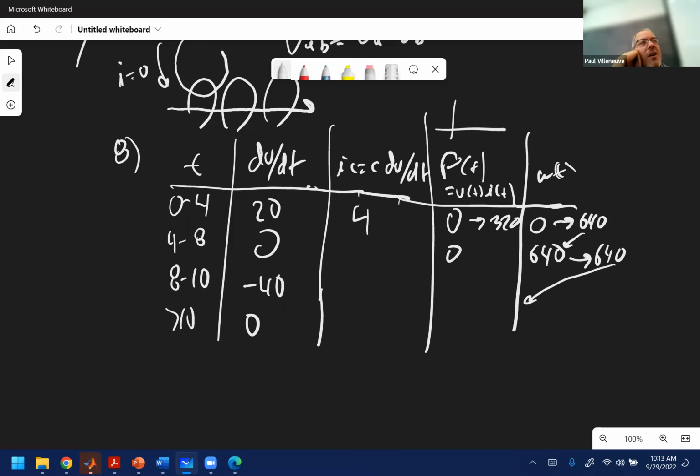But the equation for power of time is called instantaneous power. We'll see that when we start looking at AC circuit analysis. For those of you in 312, for example, the power that you're calculating in AC circuits is not an instantaneous power. It's an average power. But if you actually look at what the power calculation is, it's really take any instant in time, find the voltage and multiply it by that same instant in time current. That's how you get the power at that instant in time.